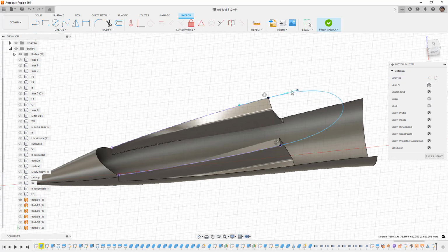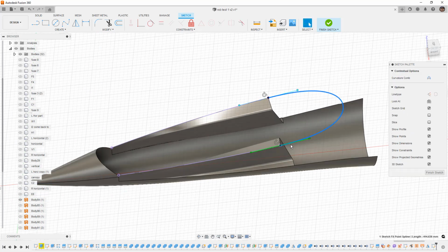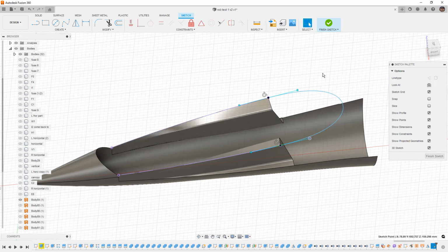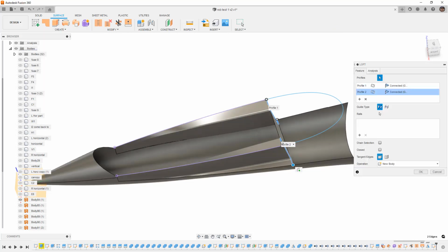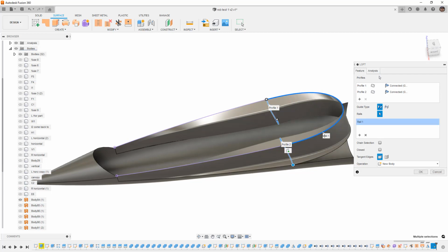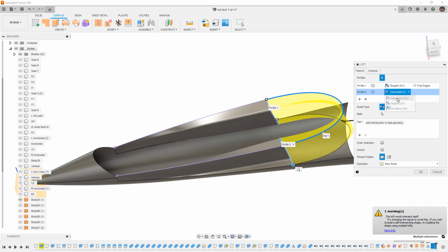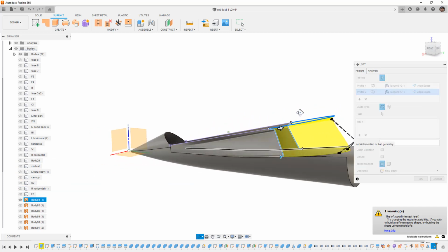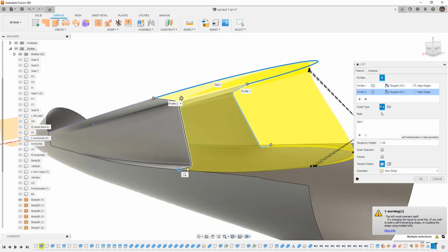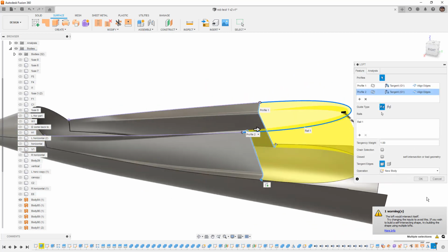The last step to this is the weight of these handles, and when we're doing this in 3D, we don't really have quite the same control that we normally would. You could do this by creating projected edges. It's just going to take a bit more time. So I'm going to finish the sketch with just that. I'm going to go back to my loft and say loft from here to here. This time I'm going to add a guide rail, and I'm going to drive this off of tangency. So once again, I'm going to try it at tangency, see if we can get it using my aligned edges or aligned to surface option. And you can see that it's still trying to fail because what's actually happening is it's sort of rolling over here. So this tells me that that isn't going to work.